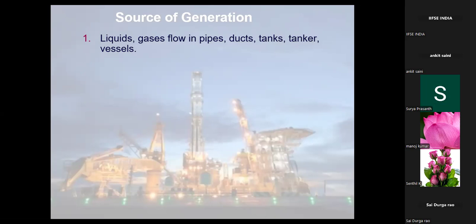That is the muffler. The spark arrestor is called the muffler. There is also earthing of the body. The body of the truck has to be given earth, and the vessel to which you are discharging also has to be earthed. Both of them have to be earthed.